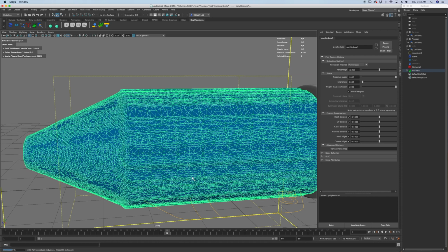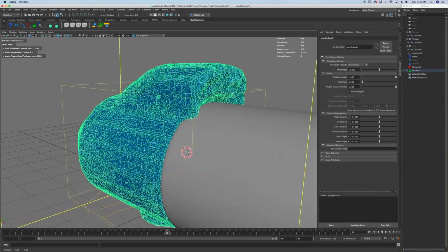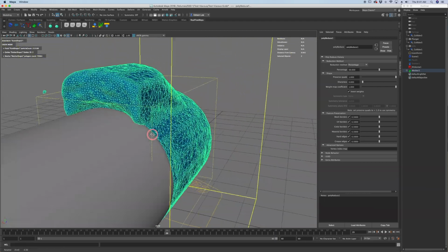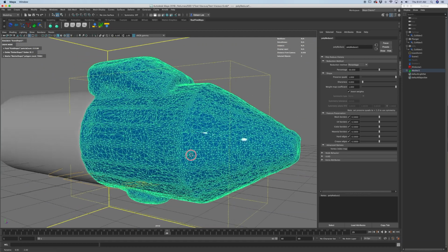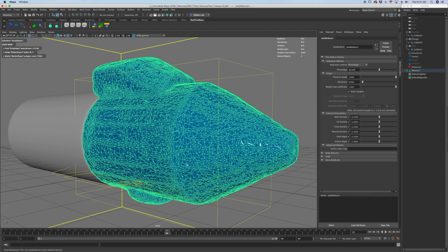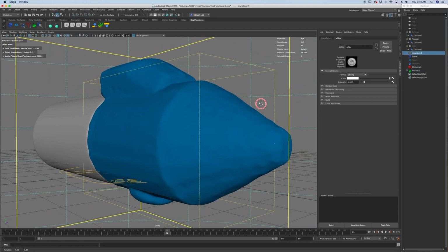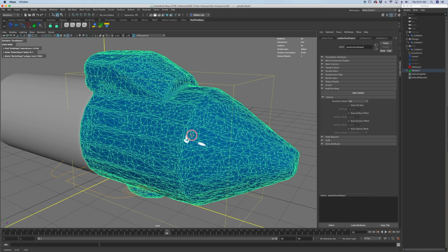Okay, and I'm going to visually inspect to see what's happening here when the jelly is put under stress. Okay, that's happening. All right, maybe I'd like to do that again. Let's see what happens if I reduce it by yet another 50%. I'm going to press G here to repeat the last command, and it's going to reduce it even more. Okay, so that's what it looks like, and with this amount of polygons, I am going to perhaps smooth it. Okay, so Maya's telling me that's still too many to smooth, so let me just do it one more time.